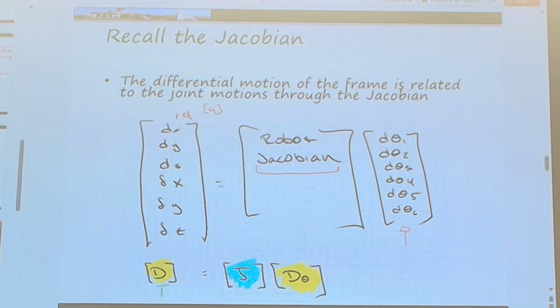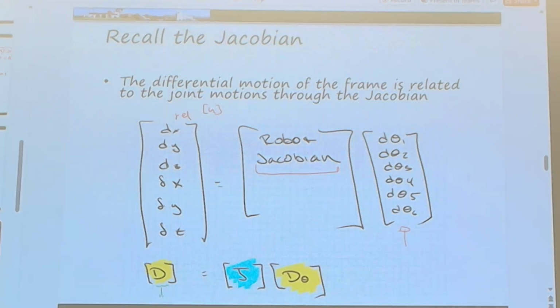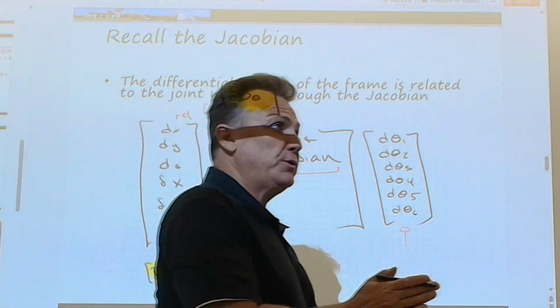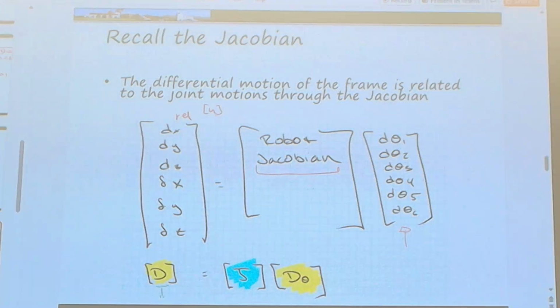We can do a servo control, but let me ask this question. This is a fundamental question. This is a very good question. It could show up on your exam. Do I control to theta, or should I control to theta dot? Theta dot. Why? Because it's velocity. And that's one thing we can control. But why can't I control the theta? You can indirectly, but you can't directly.